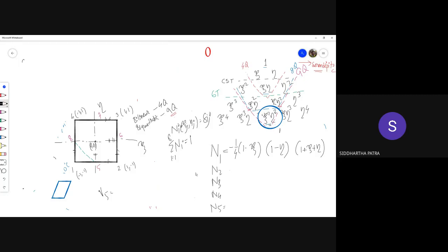And because you are taking only 3 straight lines, you are never going to get anything higher than the power 3, I mean cumulative power. You will also not be encountering any xi cube or eta cube, because for each natural coordinate there should be at least one of the terms, like 1 minus xi or 1 minus eta.